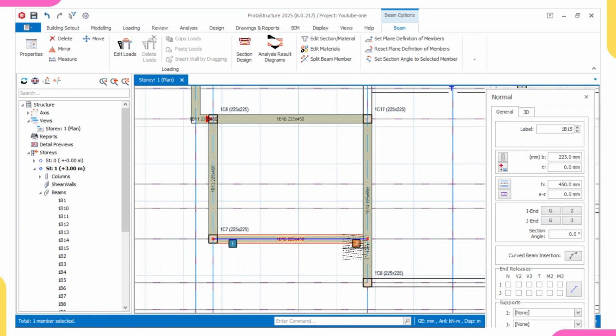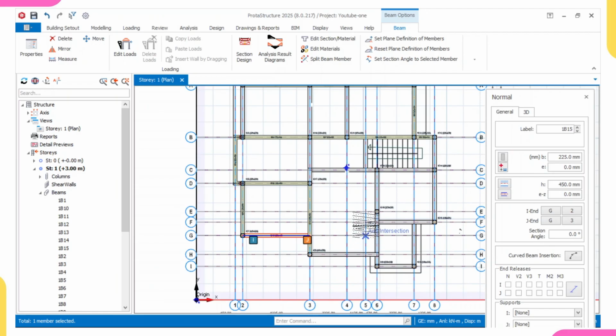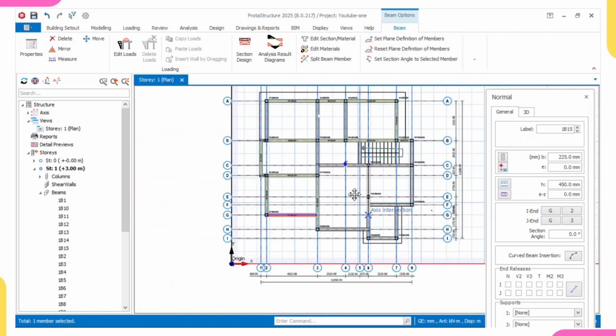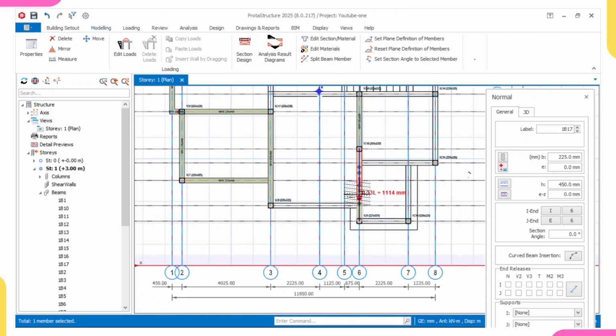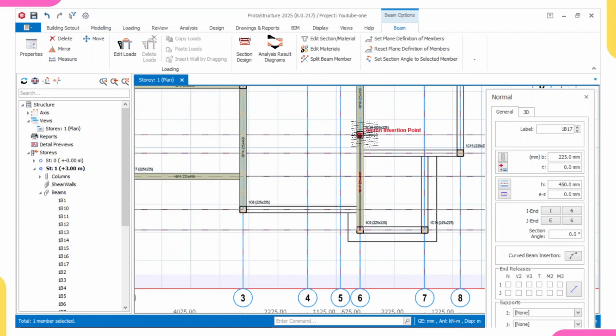So first of all, connect your primary beam. I've explained the difference between a primary beam and a secondary beam. So let's continue. If you can see now, I did this one first, from here to here, which is the primary beam. As I did this one first, that means that the cantilever sign will be showing.